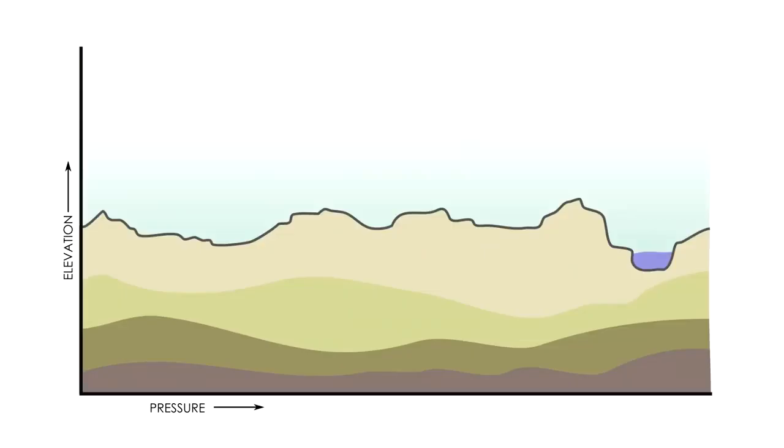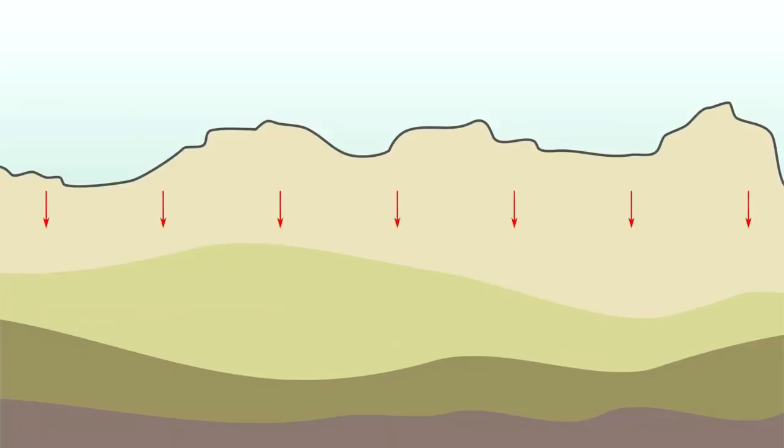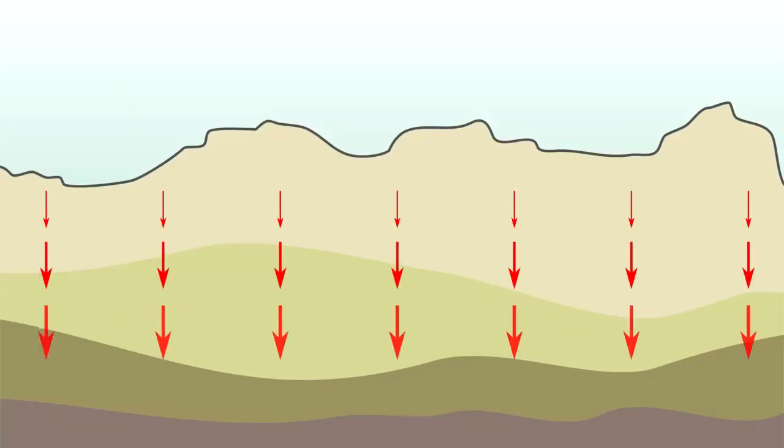Rocks are heavy. That may seem self-evident, like a lot of fundamental principles in civil engineering, but when you build things underground, it starts to become a major consideration. Just like atmospheric pressure is created by the weight of air molecules pressing down on each other, pressure exists in the subsurface of the Earth from the weight of the soil and rock above. This pressure compresses the material in the subsurface more and more the further down you go.